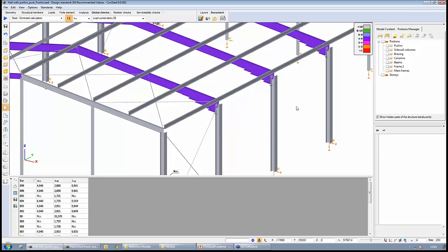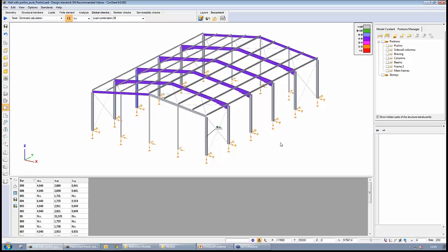So in this way we can use these special functions to optimize our three-dimensional model. We can use the partial model analysis, make convenient model portions and evaluate those portions separately, use this frame corner wizard to increase the efficiency of our design and decrease the utilization at the corners, and use this automatic elastic critical load selection for the stability design.